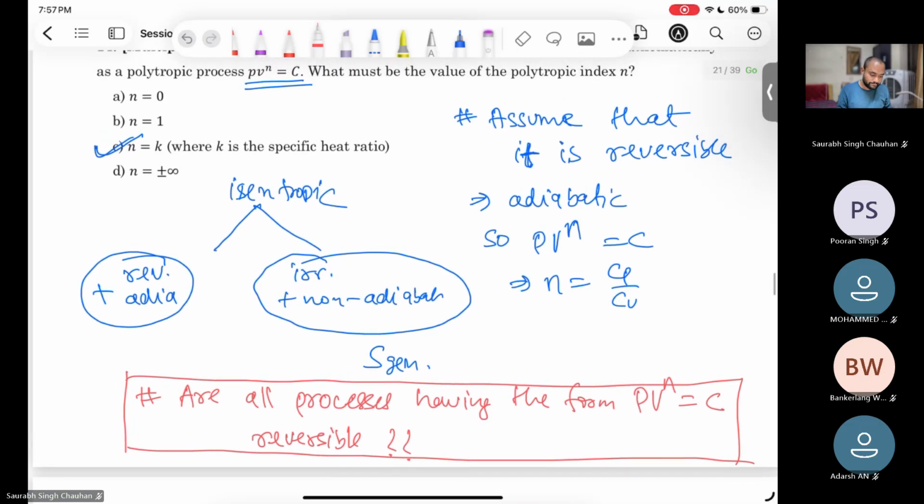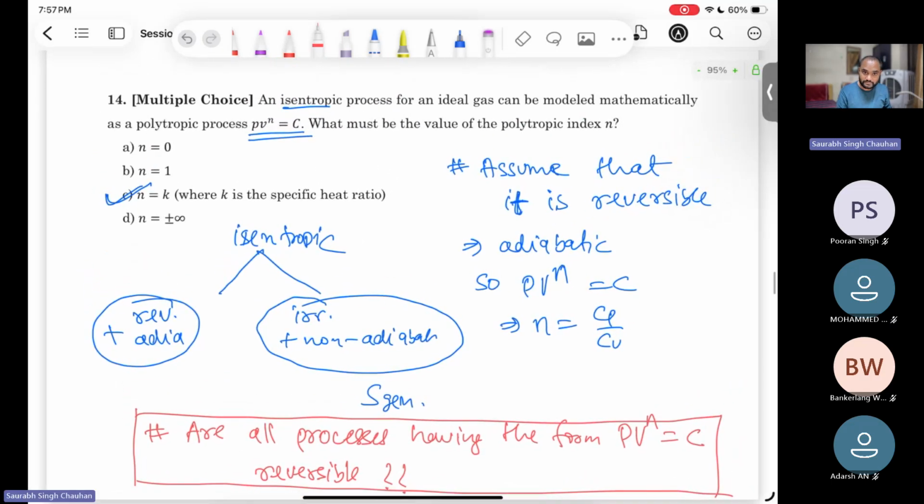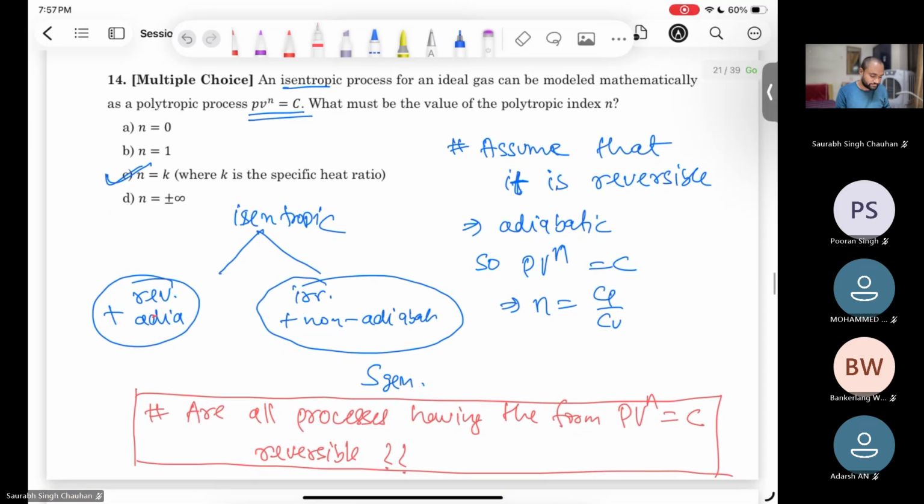That we should discuss. But in this question, I will go with case 1 because the entropy generation amount is not given. And again, I will highlight the fact that usually you encounter these types of questions for turbines and compressors, where it will be written that assume an isentropic compressor, isentropic turbine. In those cases also, you'll have to assume it is reversible adiabatic.